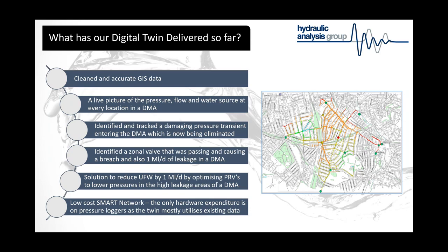This last point is that there's a lot of misgivings and misthoughts in the water industry that the water networks are steady at any point. They're steady. There's no water network in the world that's steady. It's constantly in a state of flux. There's demand changes, there's control valve operations, there's pump operations. There's no such thing as a true steady state.